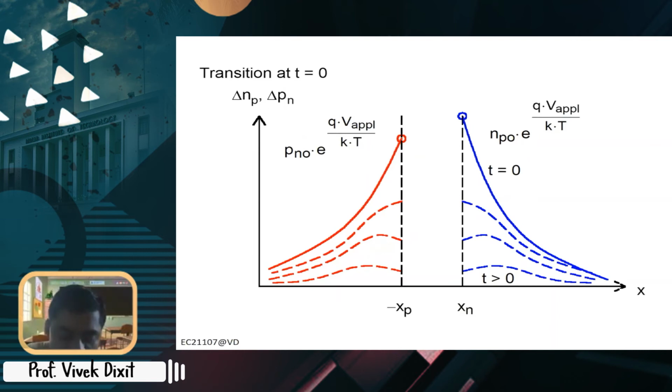Now, if you carefully look at the charge curve, so this is a minority carrier concentration, and in forward bias, the peak value is n_p0 exponential qV by kT. This is of course assuming that we applied voltage across the junction only. So if you want to be more accurate, you can write V across diode or junction, right? V_D or V_junction, right? Whatever. Now, what happens? Now you suddenly change the applied voltage to negative, right?